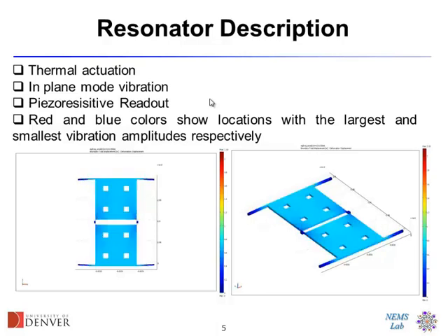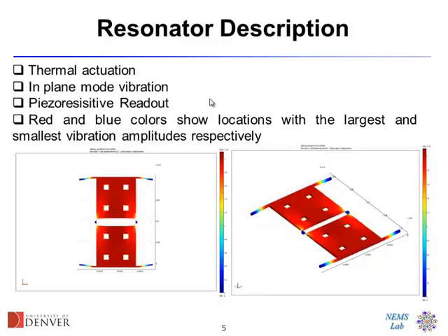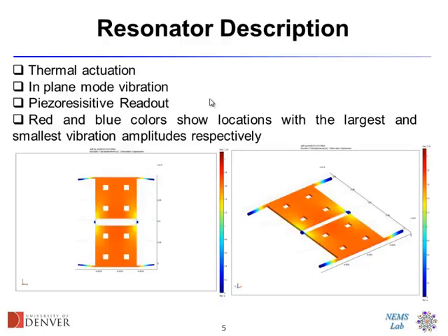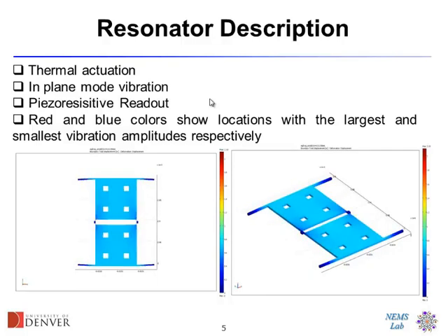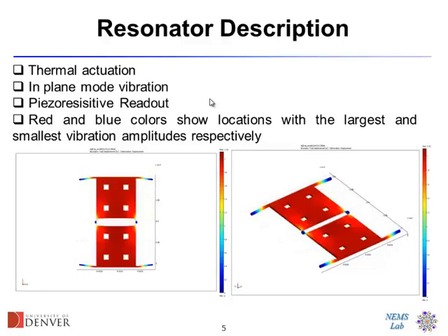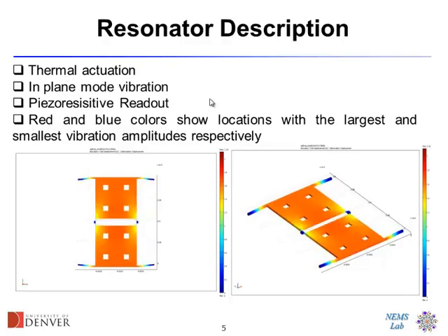And there's no small capacitive gaps that usually reduce the quality factor in air. So they can easily operate in air. The power consumption is usually a concern for these devices, but that could be reduced down to sub-milliwatts pretty easily. The key is to have very narrow actuator beams.